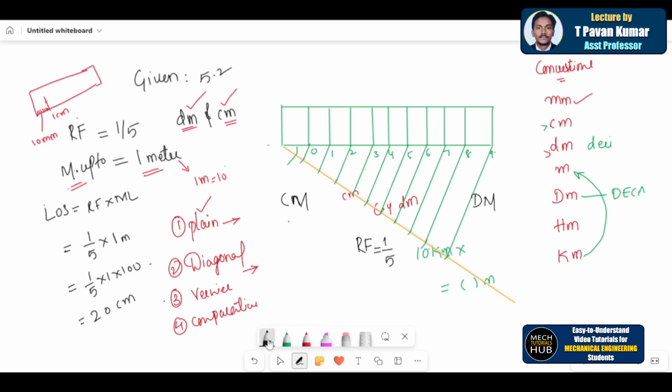For this case also same thing you are supposed to practice. Same thing in sense, draw any acute angle, divide this into number of parts and join the last end point with the 0th division, then try to divide in 10 parts. As of now I try to take only one single division. Keep it here, 0 1 2 3 4 5, this I call as 5 6 7 8 9 10, this is 10th division. In between 5 and 10 I have 4 more points.